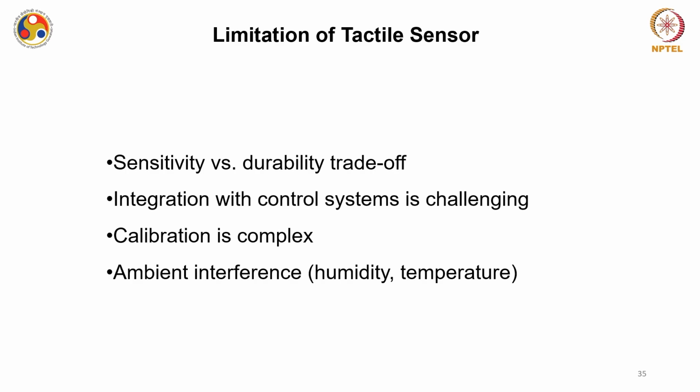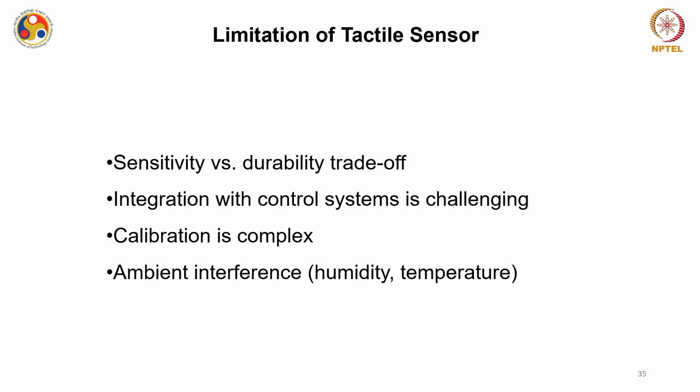Now, since we understand the fabrication process of these piezoelectric and other kinds of devices, let us see what the limitations of tactile sensors are. Please note that in all these devices there is a trade-off between sensitivity and durability. If you target durability, you have to compromise on sensitivity.